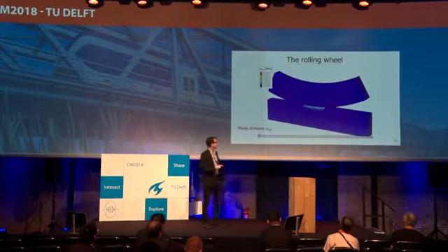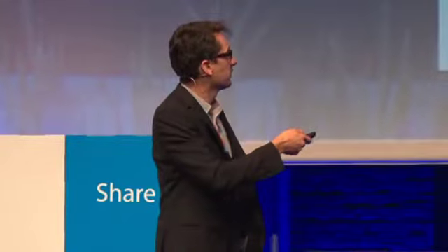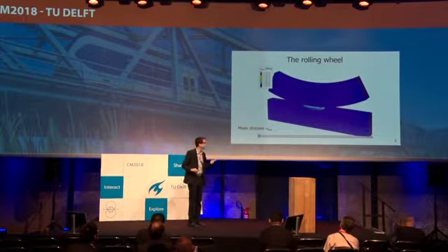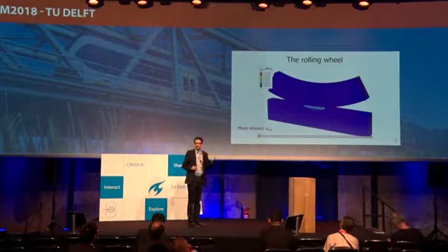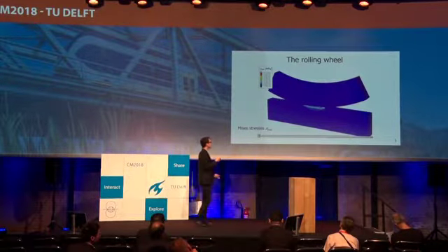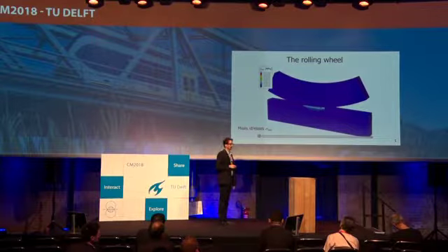Great. Now the big question is, we can roll over a distance of something like that. We can roll over a very long distance or a very short one. I think yesterday in the plenary lectures we saw that we need a certain distance of rolling for a certain contact patch to develop with slip and everything. And when we have plastic deformation, we need even a longer rolling length for something quite uniform of plastic deformation to develop. So that would be something I'll be studying in the next slides. And the other thing, of course, mesh size. What mesh size do we need to predict how much deformation we will have there?